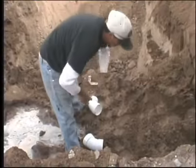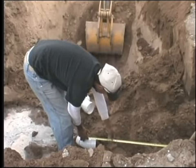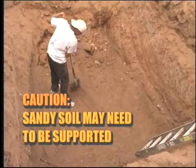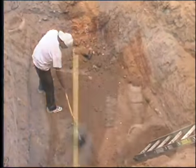A typical depth to the top of the tank inlet when the tank is 15 feet from the house is around 28 inches. A word of caution: digging a large hole may be dangerous if the soil is unstable or too sandy. The sides of the hole may need to be supported.